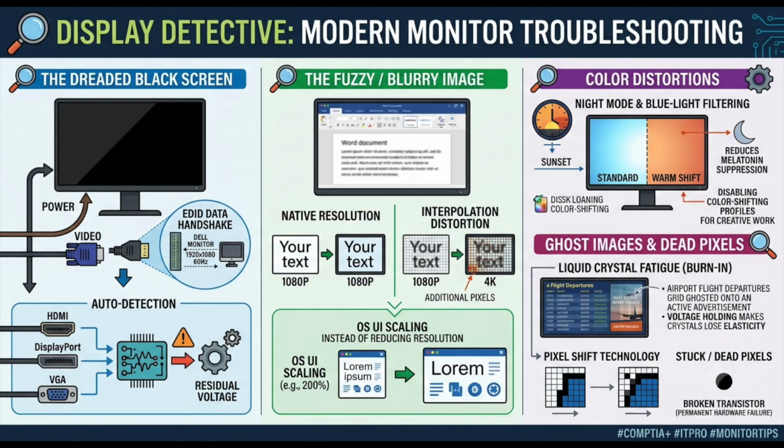It is a classic case of component mismatch and driver bugs. Hardware acceleration requires a flawless high-speed baton pass between the web browser's software, the operating system's video drivers, and the physical silicon of the graphics card. It's a complex chain. Very complex. The GPU writes the image to a memory bank called a frame buffer. If there is a slight bug in the driver, or if the graphics card is slightly out of specification, it drops the baton during the handoff.